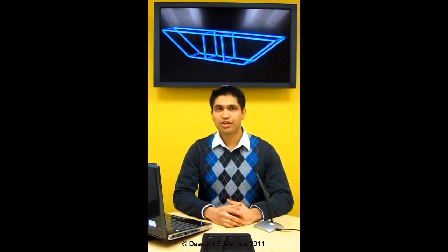When setting up the simulation in Abaqus, we will model the beam members using line segments, or more correctly wire features, just like we did in the truss analysis examples. We will then define beam profiles, create beam sections, and assign these profiles to them, and finally assign these beam sections to the wire features.